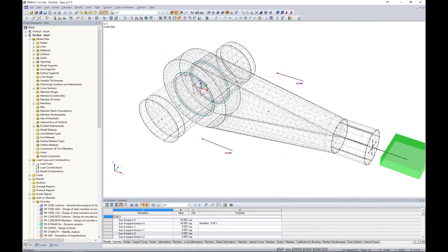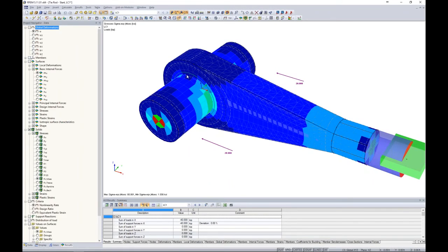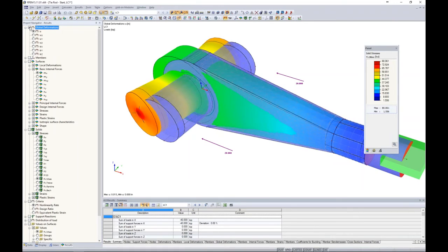Okay, so now that we have discussed what type of elements are going on here with this tie rod, let me turn this back into a rendered view. We want to run our analysis. Now, in reality, when we run our analysis, we should take a look again at the deformations. That's kind of always my advice on viewing if we're seeing our expected behavior.